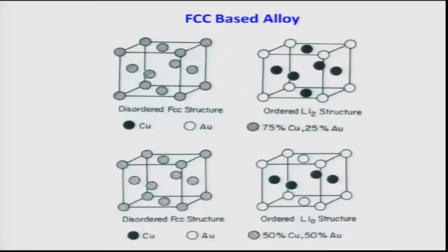Okay, let us give examples of that. Just now I told you the examples of the Cu3Au structure. So, in a disordered solution, which is the high temperature alpha phase, as you see here, there is no specific positions where specific atoms can go. It is an average situation, like the cube corner or face center positions can be occupied by either copper or gold atoms. There is no specific way of demarcating that.